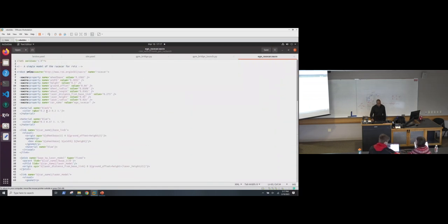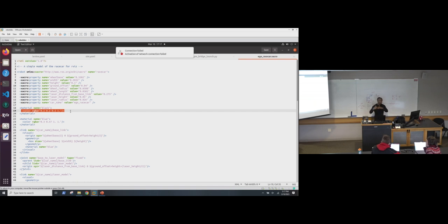But in realistic terms, when I do this here, a mature property, I will actually put in mass in there. So if we adjust that mass with that velocity, it's not going to move. If I give it a 0.5 x direction, it's not going to move as much there. So this is similarly in an ideal environment. They could behave a little bit differently in the simulation versus your reality because you don't have that information. The more you describe the information, the more likely it's going to happen.